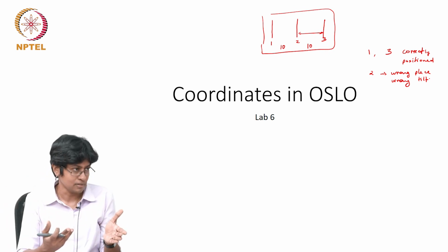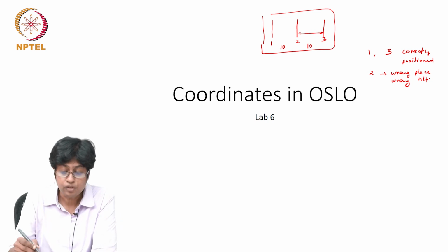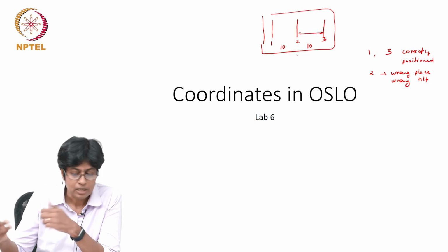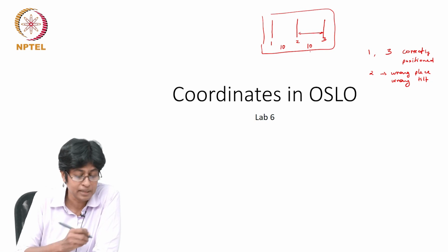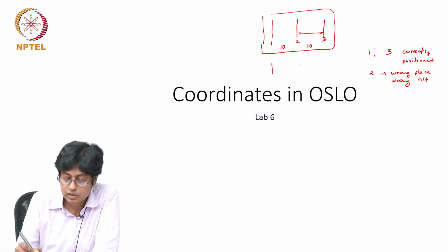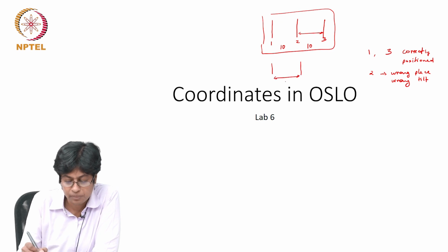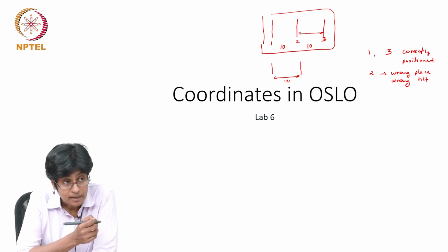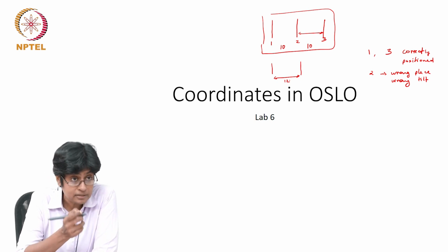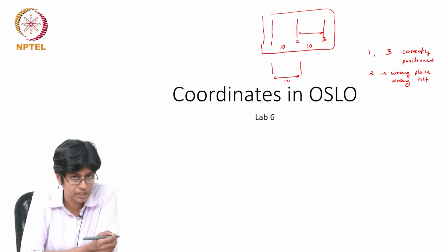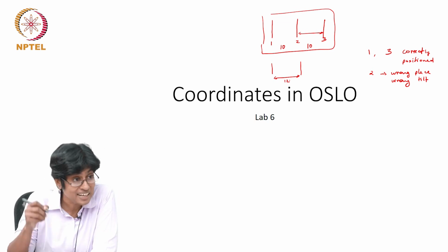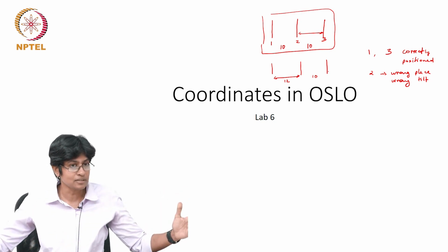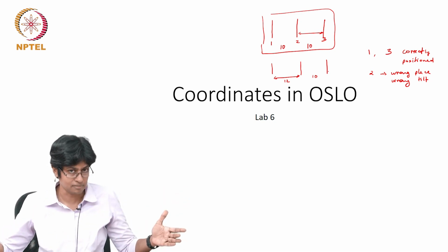In your current techniques, let's say element 2 had a delta z error, so it should have been 10 millimeters from element 1, but instead it was 12 millimeters. So there's a 2 millimeter error. Element 3 is still 10 millimeters away from the original location of element 2. But if I just write 10 now, I've changed my system, because now the entire length is 22 millimeters, not 20.